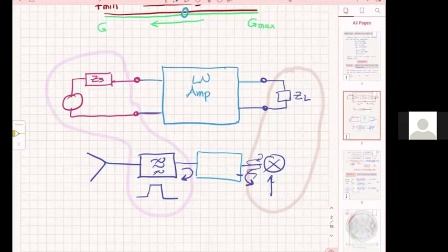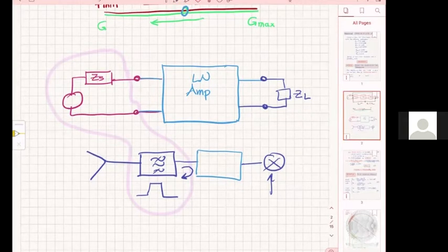All right, but as I said, the output is less critical than the input, because at the input, you lose power, you're going to have even less power to amplify, and your gain is not going to be good enough. So how do we define the requirement that this gamma here, which is the gamma practically right here, this gamma in, is small? By a VSWR.